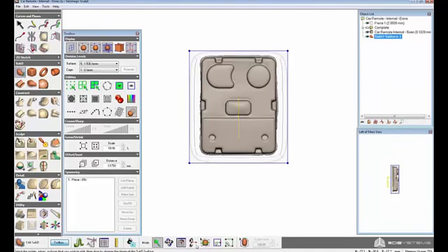And what I'm going to do is start adding more of these lines, these interpolation lines here, because these are control lines, I should say. Because the more lines I have, the more control I will have over the shape. So to quickly do that, I'm just going to use this loop tool, which will create a loop where I click. And remember, I have symmetry turned on, so wherever I put them, it's going to do symmetry. And you notice that I can click anywhere along this line, but the software is going to help tell me where some key points are.